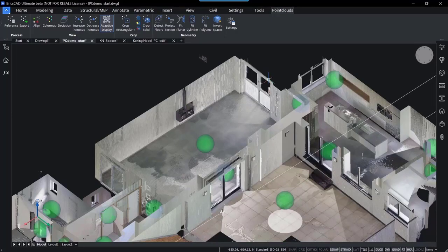Points can have their color information or location information in it, and a point cloud can also contain certain information on scan positions. When we have fixed scan positions, we call it structured point clouds. And unstructured point clouds are the ones that don't have information on the scan positions because they were made with, for example, a mobile scanner, like a moving drone. When you work with structured point clouds, we will use this information during import.